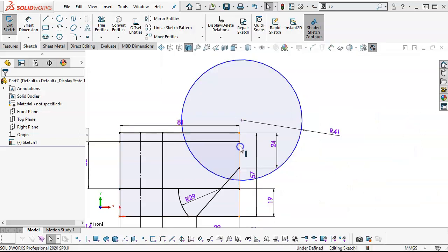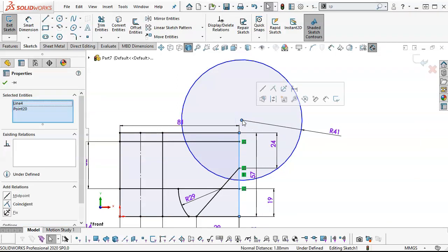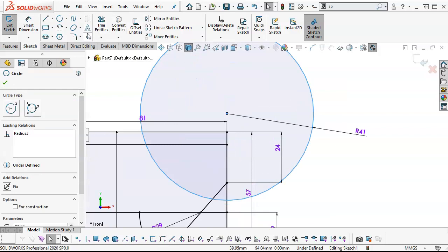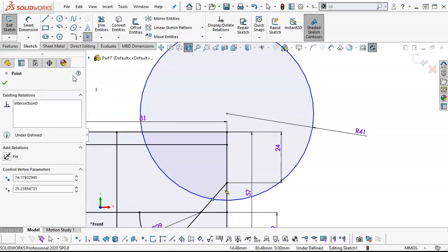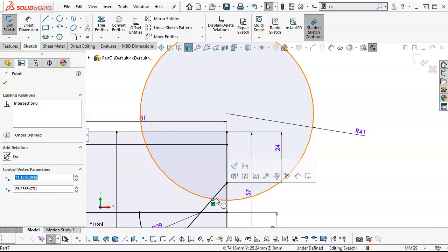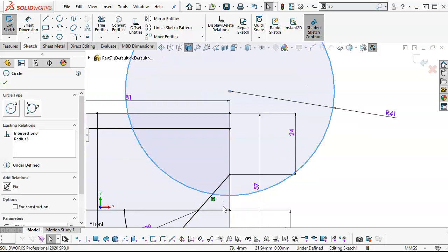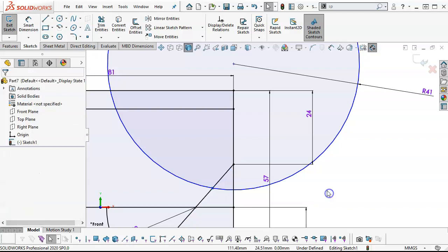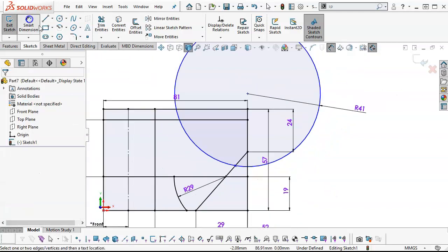So I'm going to make the line and the center point coincident. To help with that intersection, I'm going to place a point, and could probably barely see the relation that it pulled, but it was the intersection. If it doesn't give me an intersection, then I'll select Control Select, do coincident, go back, pick up the circle and arc, do coincident, and that'll have the same effect.